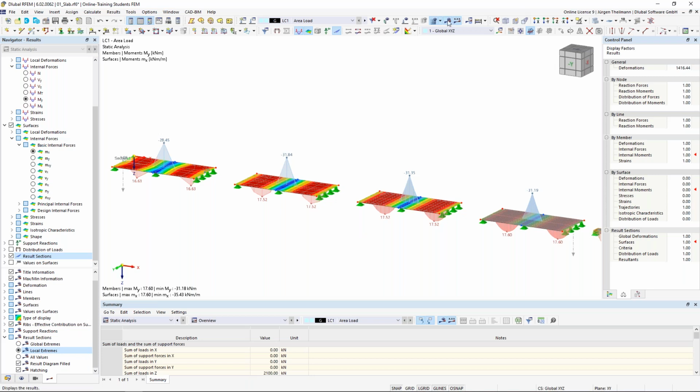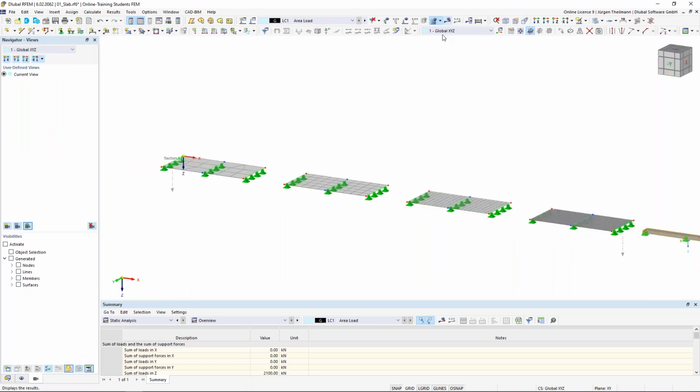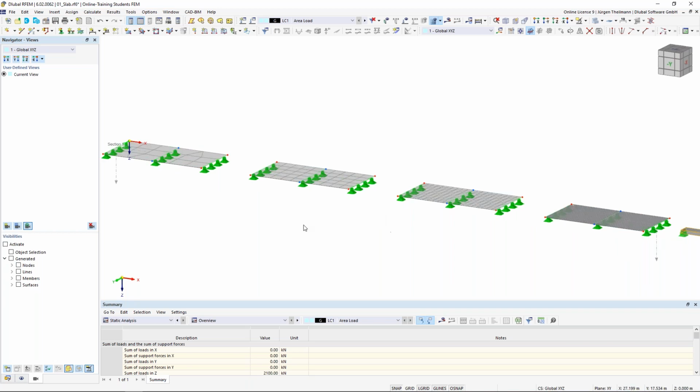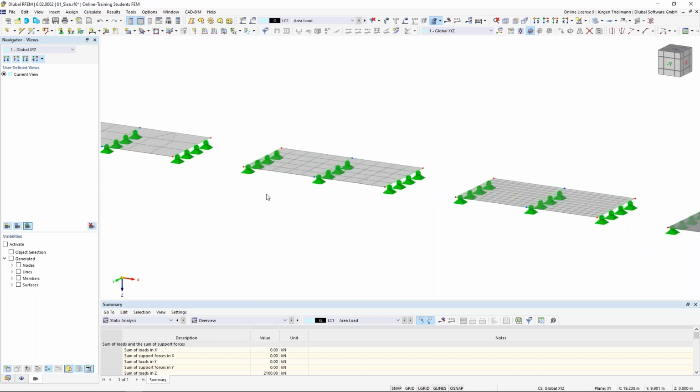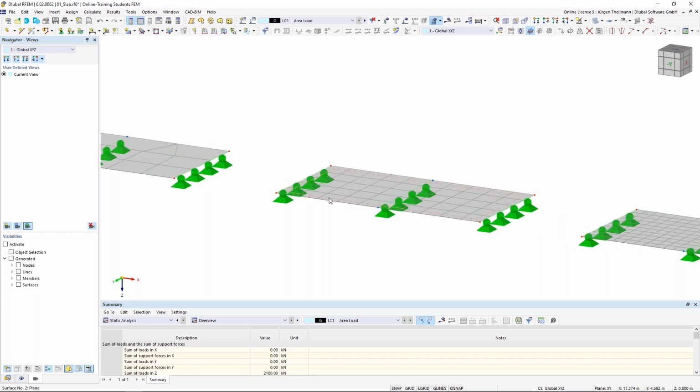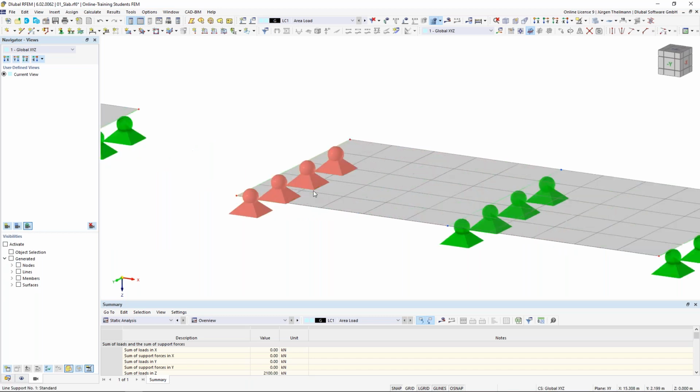I just hide the results and also give you a little bit of a rule which you can hang on to, is that usually you have a minimum of 3, 4, 5 FE elements alongside one structural element.